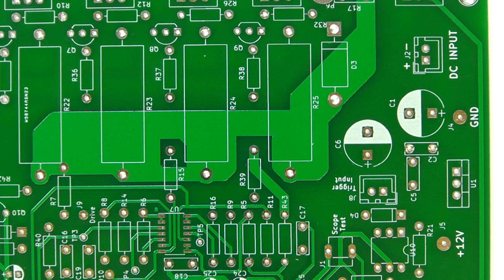with the leakage current when we have no load, that small leakage current, and also fix the issue where we have the voltage on the display fluctuating when the fan kicks in, and that's caused actually by some grounding problems on the printed circuit board. Now, one way of solving that is to add some additional grounding, which is what we're going to do today, with some heavy gauge copper wire.